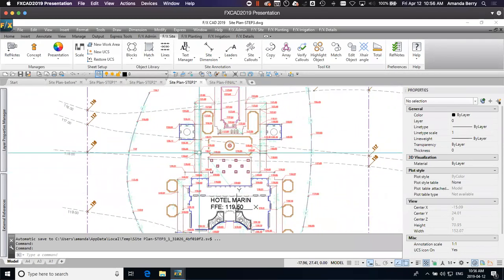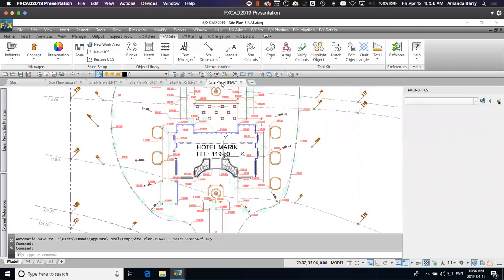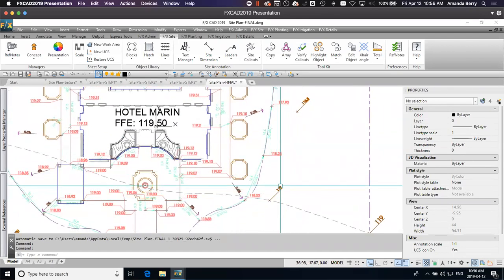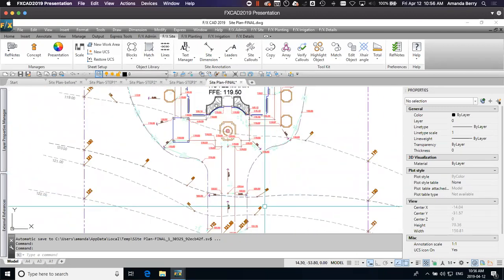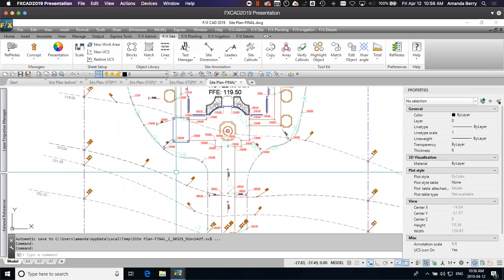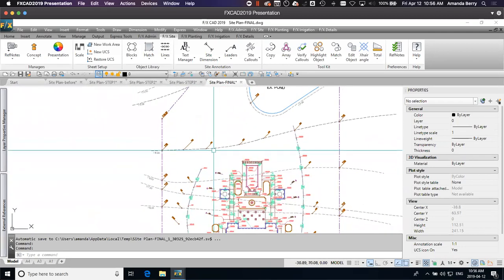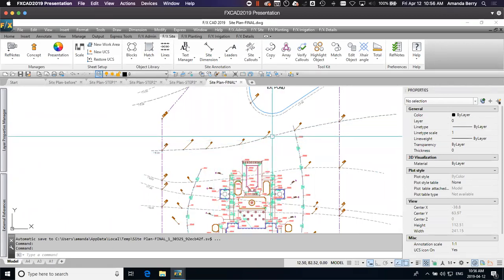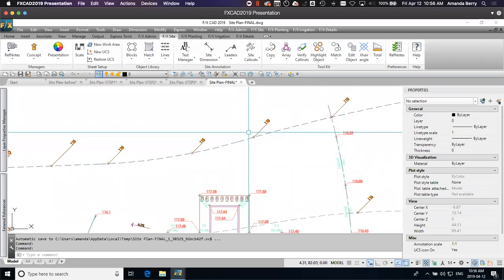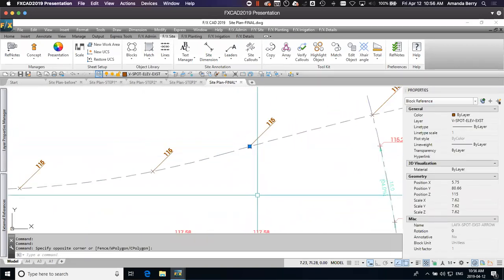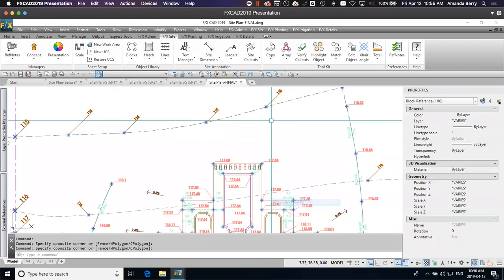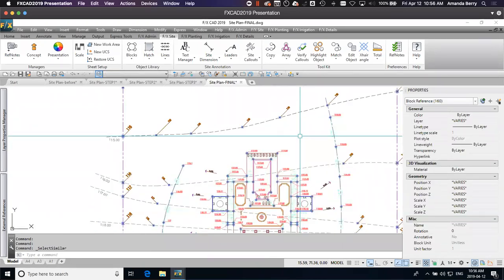And once you've got all this together, really easily, what you can do is I just started using that existing spot elevation to start creating spots at a relative extent of grading to make sure that everything conformed with the existing grading for popping it over to 3D. And once I got all of that, with this kind of plan, you can just grab that existing spot elevation block and grab this proposed spot elevation block. I right click and do select similar to grab them all. And I basically just did a W block.